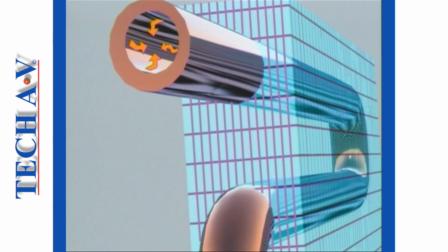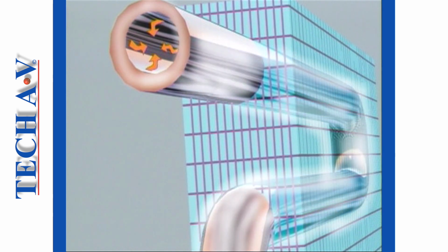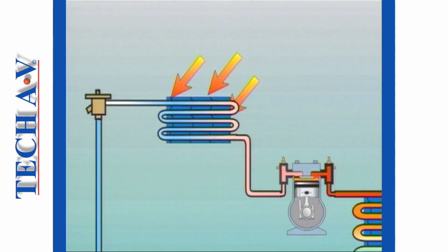During this change of state, or evaporation process, heat is absorbed by the refrigerant out of the tubing. The coil becomes cold and in turn absorbs the heat contained in the surrounding air. This heat is then carried off by the vapor flow.